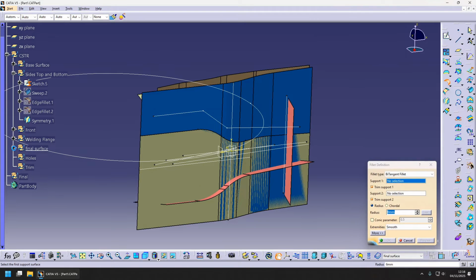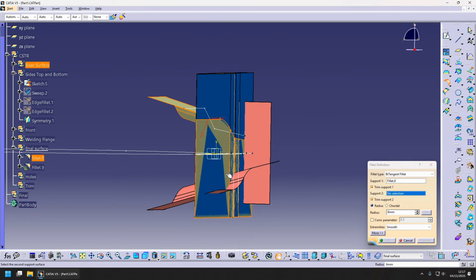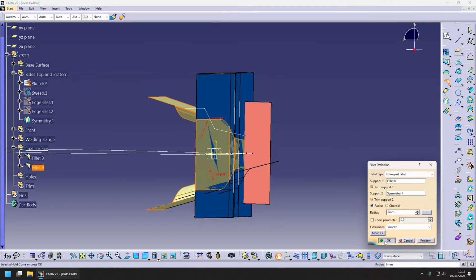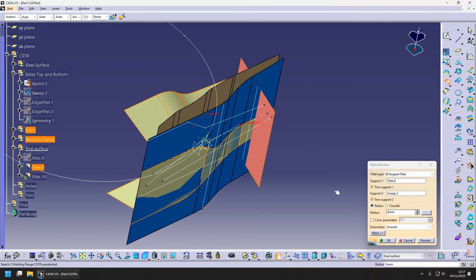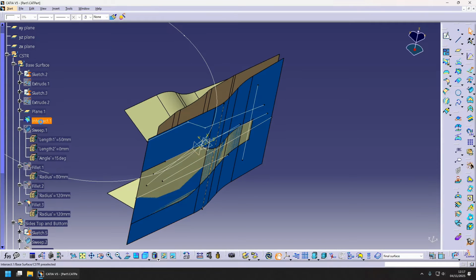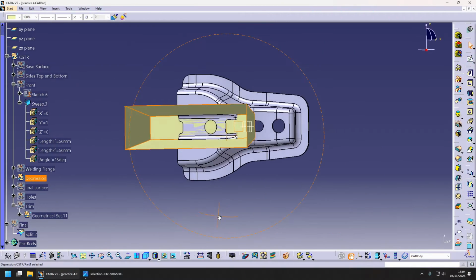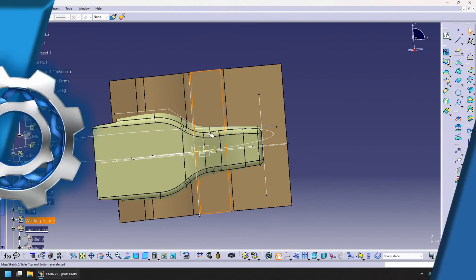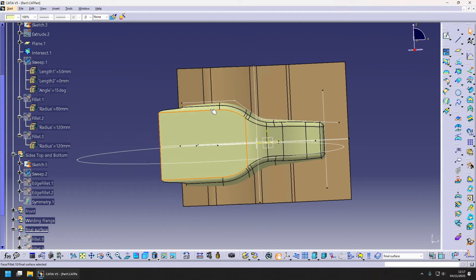Okay, now we take this fillet that we did and fillet it to the other side, also with 6mm, and there's one side left, which is the front side, also 6mm. That looks about right. I guess we don't need to see this anymore, so we hide it. This small depression in the top surface is also a separate feature. Before we add the welding surface to this shape, I would rather add the small depression here as well.